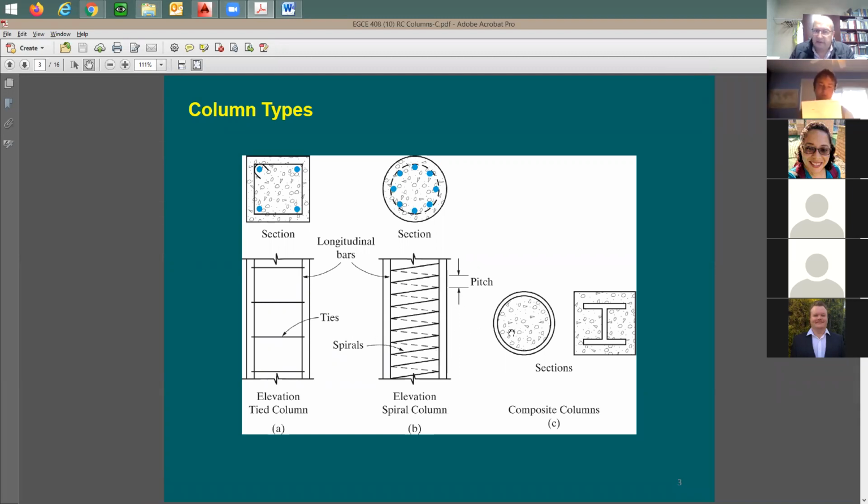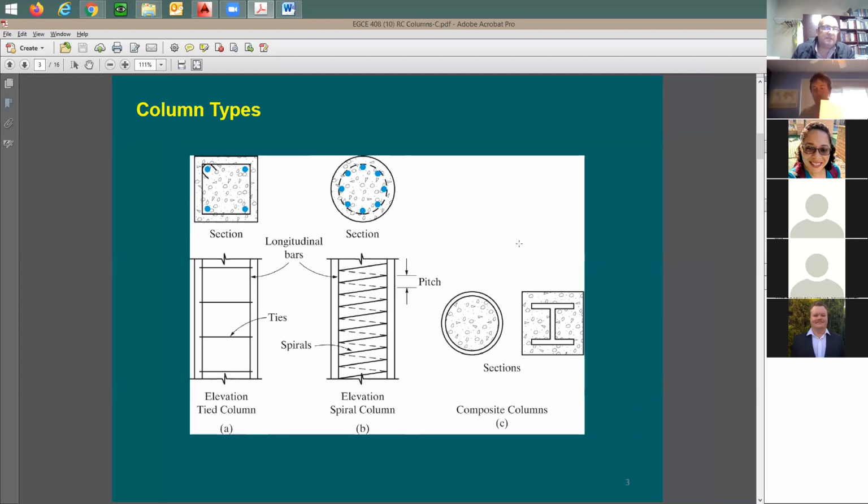Once you contain it, you provide lots of pressure around this concrete column, and this helps the axial load capacity. Here's the axial load, and this lateral restraint, we call confinement, meaning that here you provide more confinement than what you provided here. And this confinement is going to enhance the concrete properties.